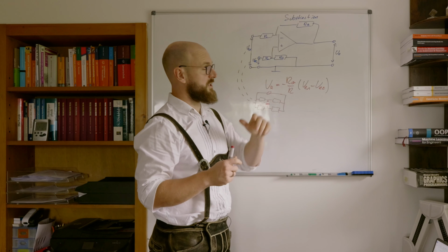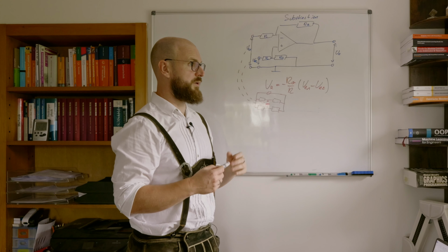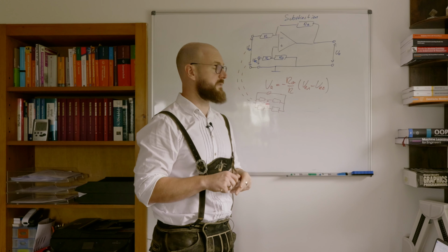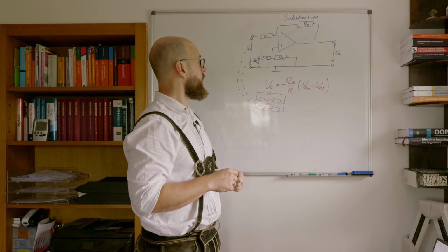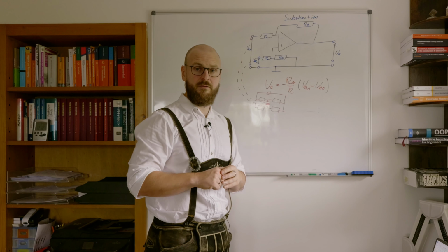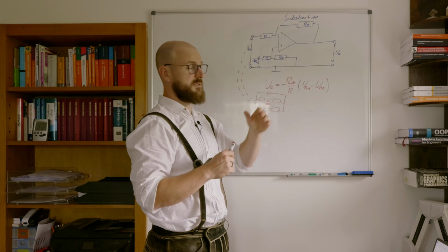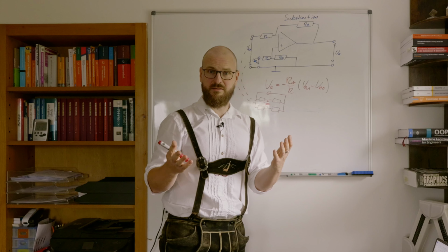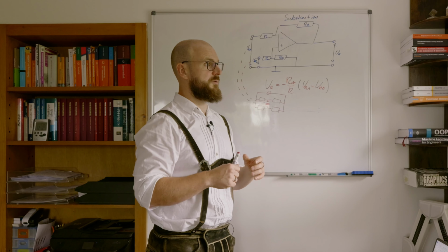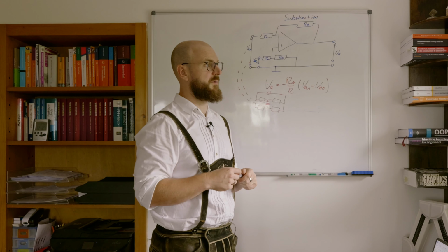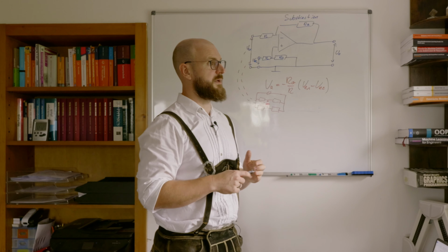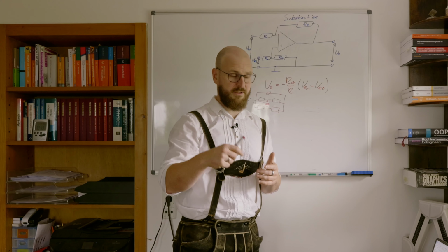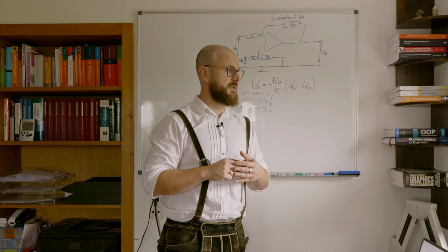Often subtraction amplifiers are combined with impedance converters or electrometer amplifiers, which allow then to amplify those voltages and then to subtract them, all together built into a difference amplifier, an instrumentation amplifier. There's some material about these things in the training exercises you have access to via the artificial intelligence.